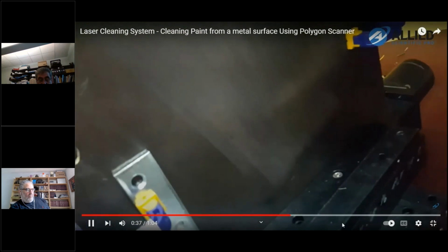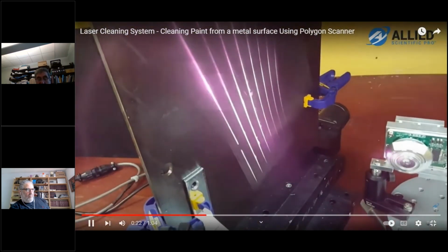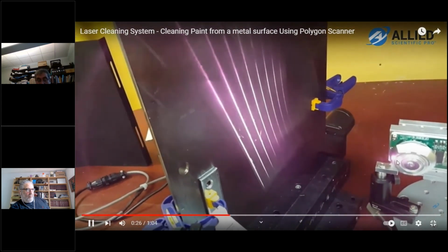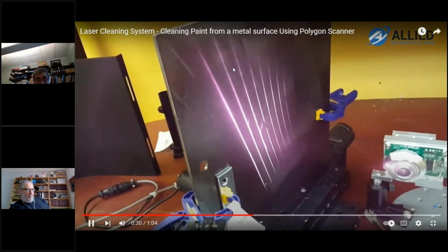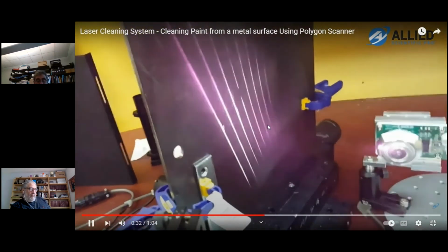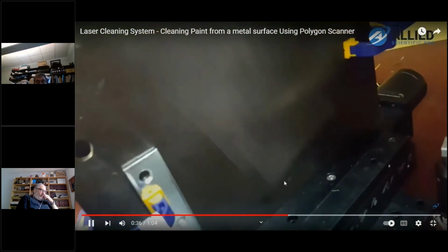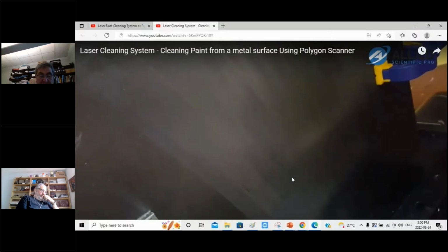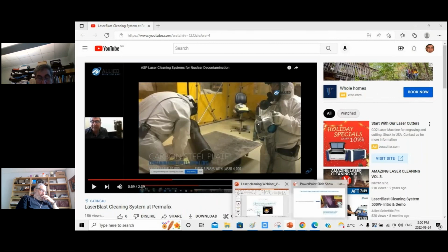So here, let me try again. In our laser cleaner, the 300-watt system, we use a polygon scanner, and all the facets are aligned, so there will be only one line, not 8 lines. So this is very useful for faster scanning speeds, and it could also tolerate higher powers. Okay, next one.